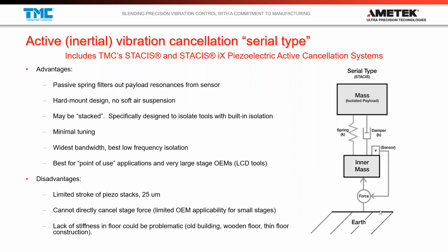And what that allows you to do using these stiff components is to really take out those low frequency resonances that are inherent in a parallel type system and support your entire system using stiffer high frequency components. And there's a real advantage to that when it comes to floor vibration, because there's really no amplification, or very, very little amplification of floor noise coming in here.